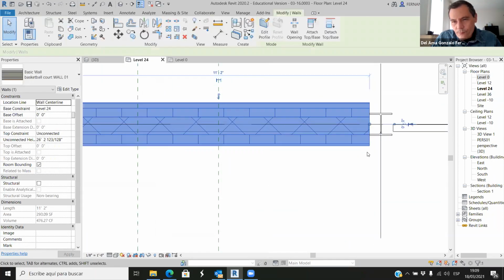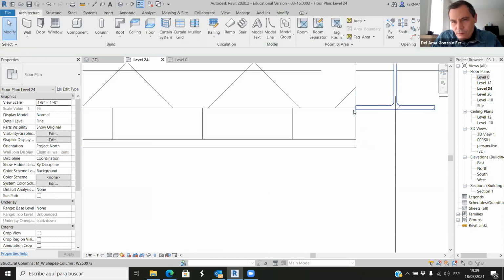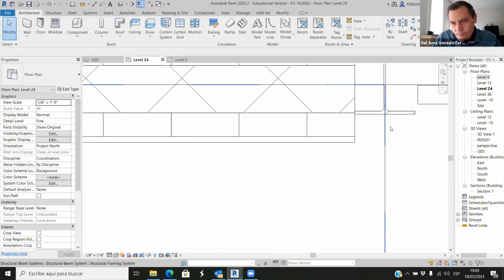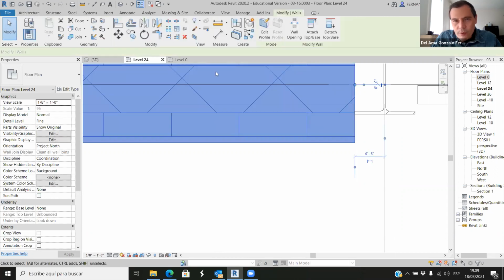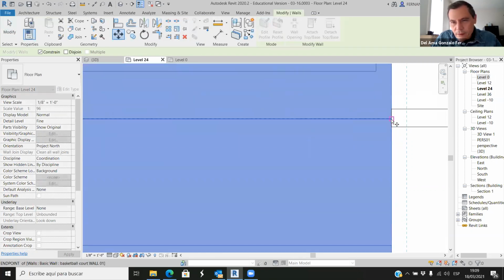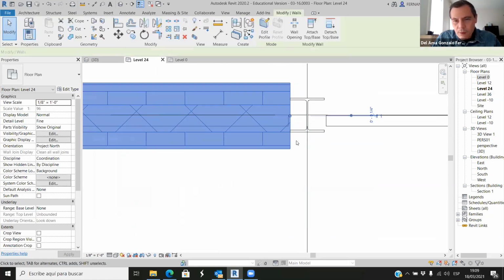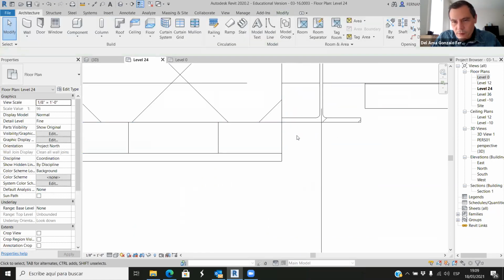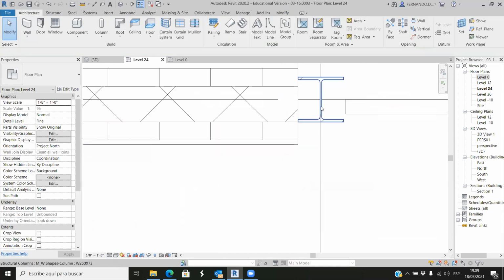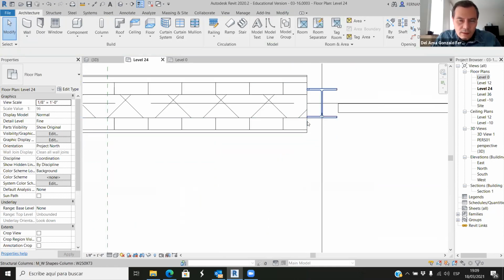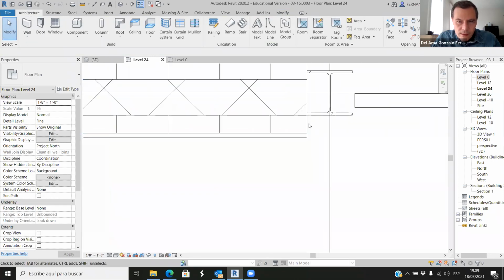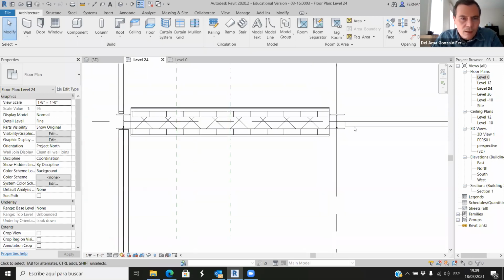And now, if this is the thermal insulation, we have to move this thermal insulation in this direction. So we can move this slightly here. Okay, so when we create parts, we can move the thermal insulation, and this layer will be hiding the structural element here. It will be exposed outside, but we won't see this element inside, and we will solve that thermal breach. Well, that's good to start.